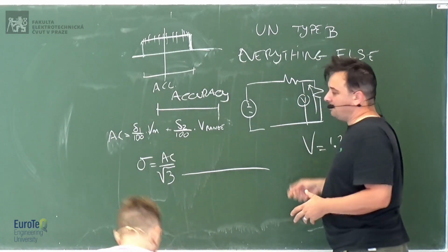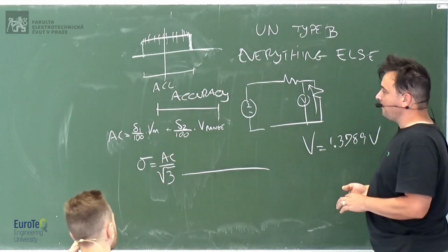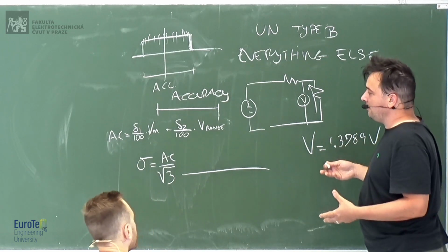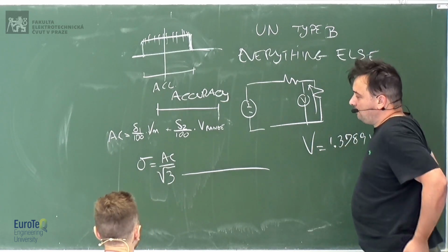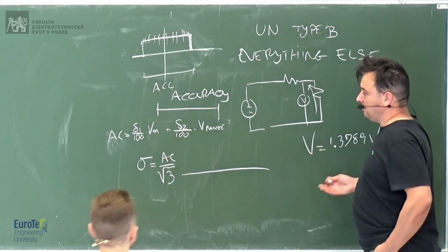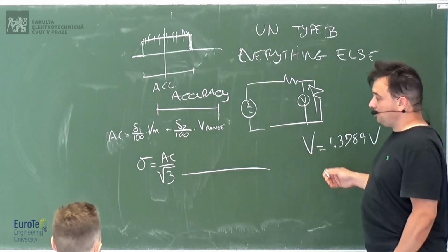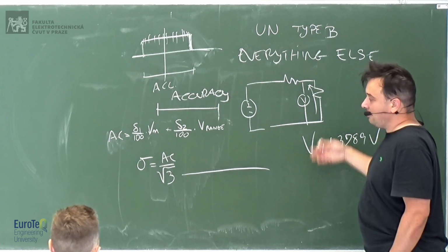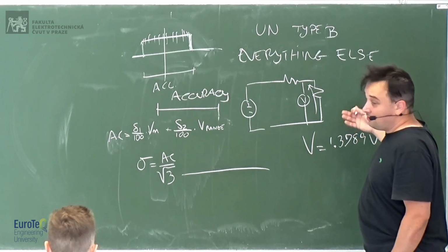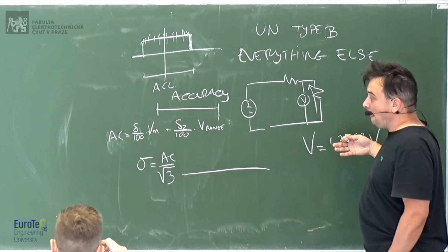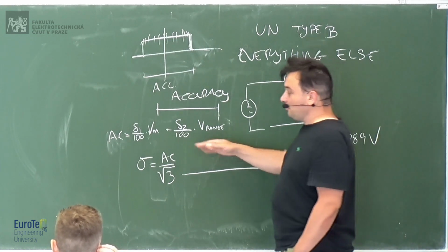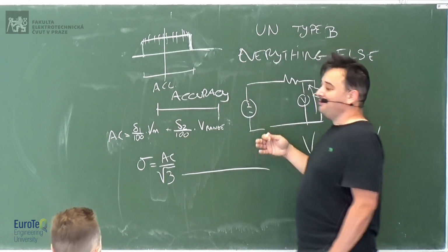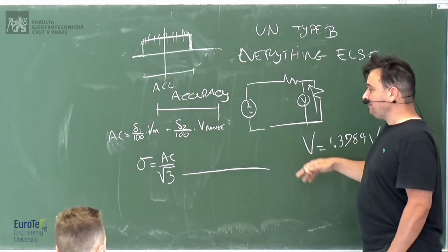When you put some instrument inside your circuit to measure something, what you have to do is take the manual of the instrument and check the accuracy specification of the instrument, which is one parameter. If the instrument is good, they have to give you that, okay? So you expect them to make some calibration before selling you the instrument, and theoretically you are supposed to calibrate it periodically.